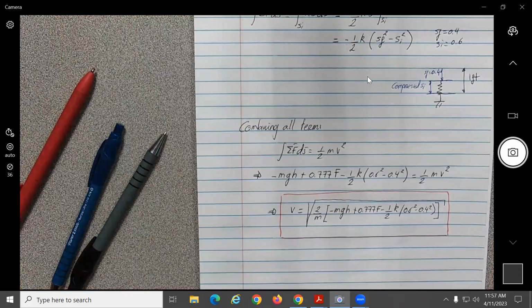Yes. So why is it again that for the work done by the spring, you denoted it as negative? Basically, what we're discussing is that initially this is the spring. If you put weight on top, it's going to be compressed. How much is it compressed? 0.6. Now the work done by the spring until it gets back to its unstretched position, is that going to be positive or negative work? The force is going to be in the same direction as the deformation, no?